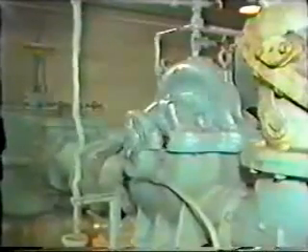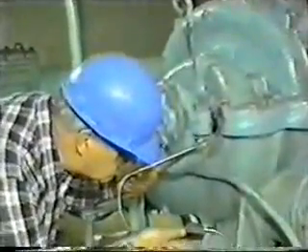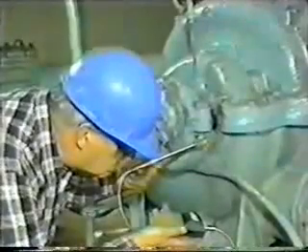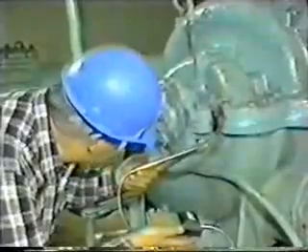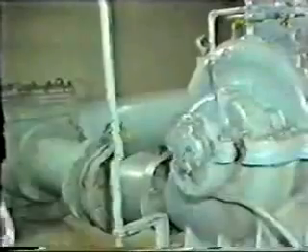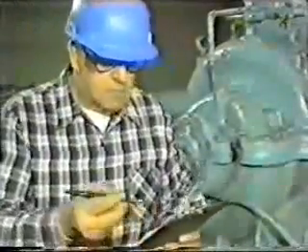The area on this pump looks properly clean. Check the temperature on the bearing. Follow your facility procedures for making this type of check. In our case, Gene uses a pyrometer to get an accurate temperature reading. The temperature has increased slightly since the operator last took a reading, but it's still within the acceptable range and doesn't warrant shutting down the pump.